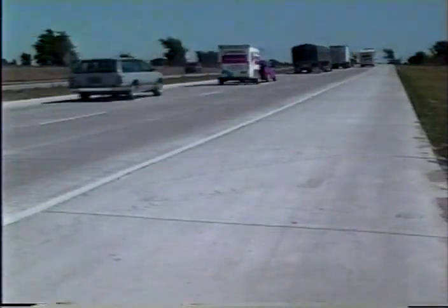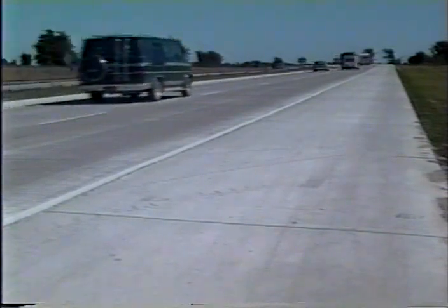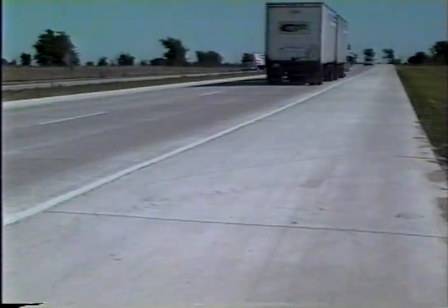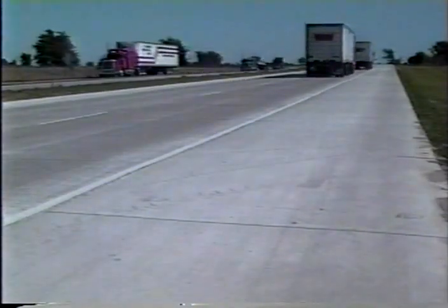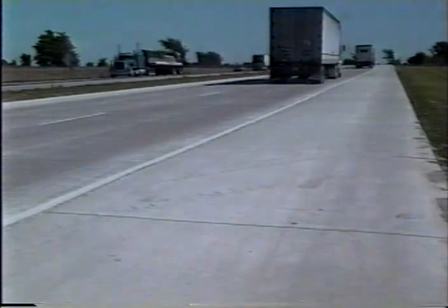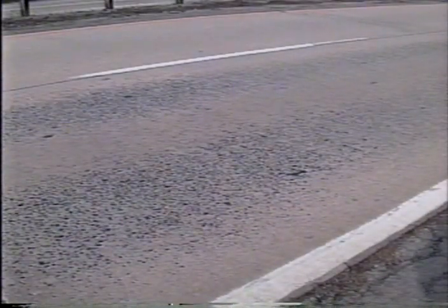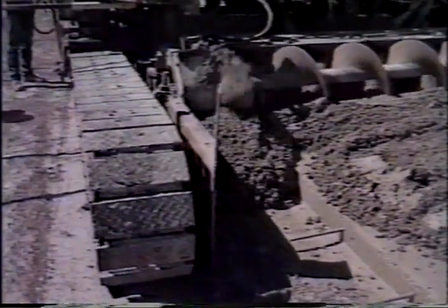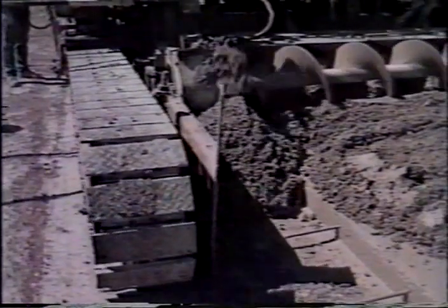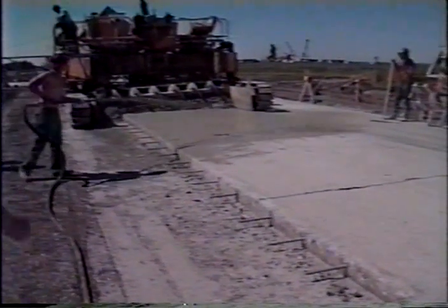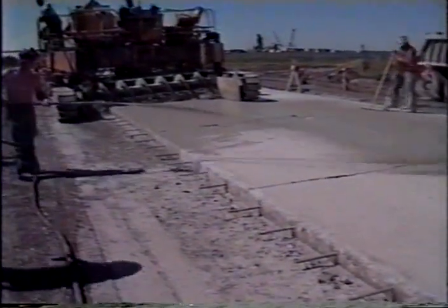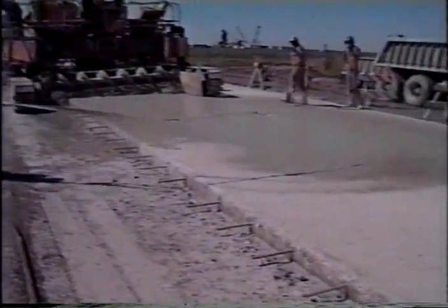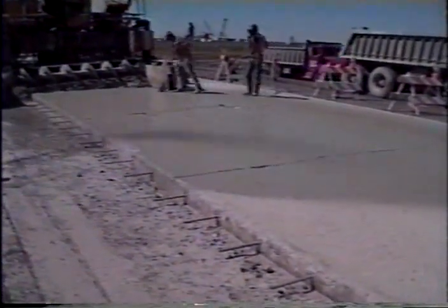As I said earlier, a bonded overlay increases the pavement's structural capacity, so it's particularly useful when truck traffic increases beyond the expected level. But it also corrects surface problems such as severe roughness or low skid resistance. Bonding a relatively thin layer of concrete to an existing concrete pavement can greatly reduce the critical stresses in the slab. So one of the keys to improving structural capacity is to provide a good bond between the overlay and the base concrete. That way the two will act monolithically.